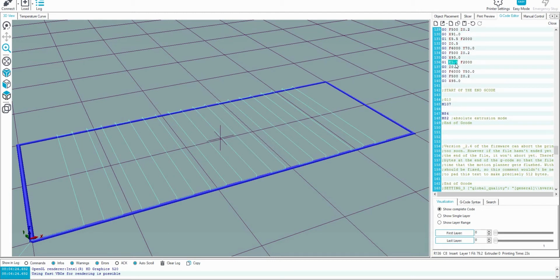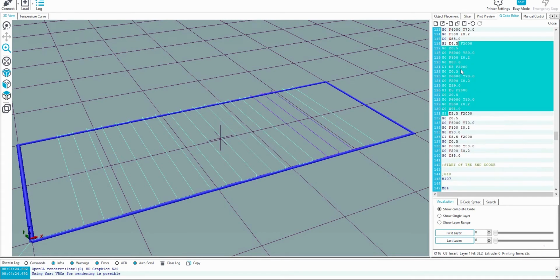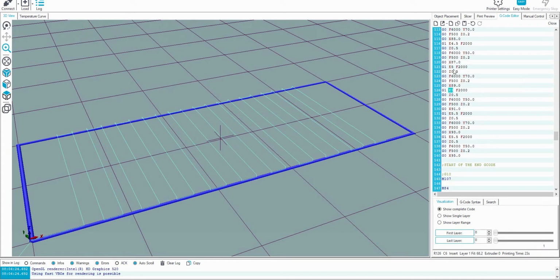For the final line, it's 5.5, and the second last line before it, whereas for the previous pair of lines it was 5, for the previous pair of lines it was 4.5, so we've correctly changed our extrusion, so it's extruding 0.5 millimeters cubed more for each pair of lines. So then we can identify what's the best amount of extrusion to get nice consistent strings.